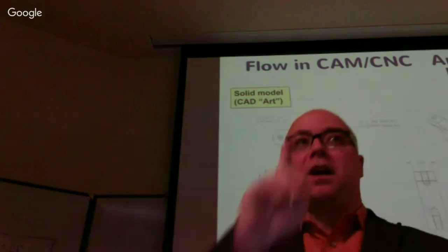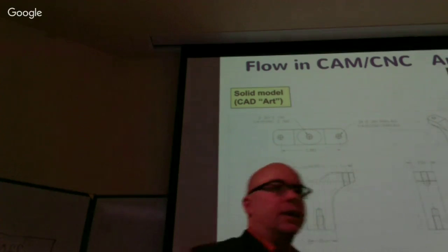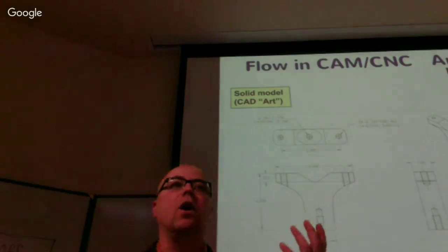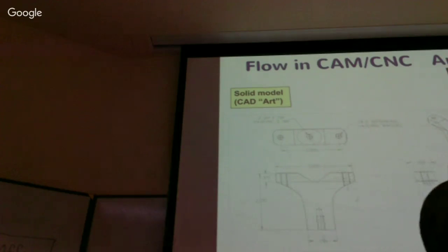So the mill drill center actually cuts 2 of the operations because it's really fast. At the same time, the VM2 is cutting 1 of the operations. So we have 3 parts in process at any point in time. And every, I think, 4.5, 5 minutes, a part comes out finished. So, all right. So we're going to use 2 different milling machines, but you could do it all in 1 machine. It would just take longer. So we've decided which machine to use.